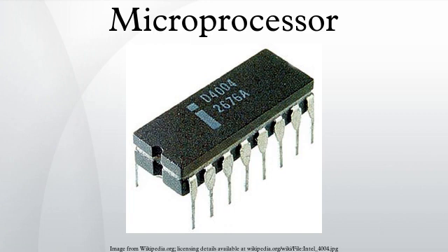32-bit designs. 16-bit designs had only been on the market briefly when 32-bit implementations started to appear. The most significant of the 32-bit designs is the Motorola MC68000, introduced in 1979. The 68K, as it was widely known, had 32-bit registers in its programming model but used 16-bit internal data paths, 3 16-bit arithmetic logic units, and a 16-bit external data bus, and externally supported only 24-bit addresses.